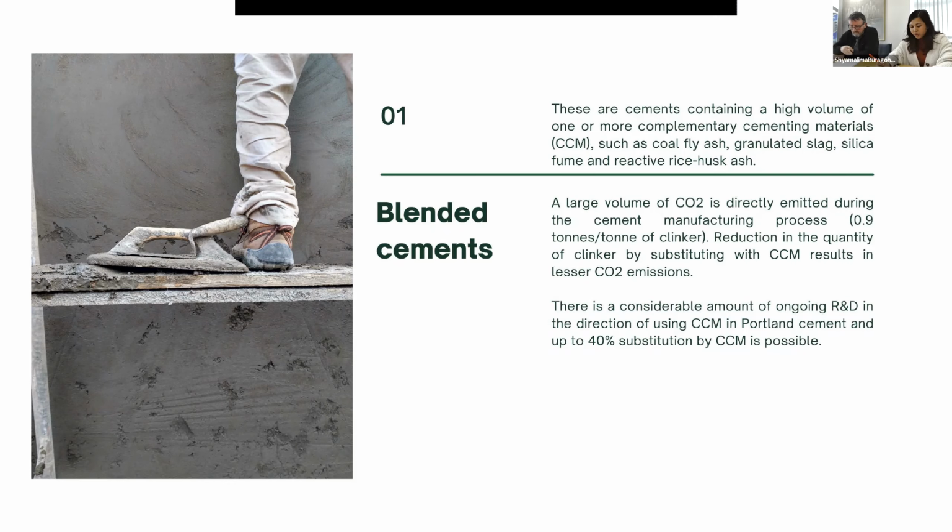It can be used as a zero carbon building material in several ways. Firstly, its carbon footprint is reduced because the use of fly ash and slag reduces the amount of clinker which is required to produce cement. Secondly, blended cement can be used to produce low carbon concrete by combining it with other materials such as recycled aggregates or fly ash that has very low carbon footprint. Overall, blended cement has the potential to be a valuable tool in reducing the carbon footprint of a building and helping the construction industry to promote sustainable building practices.